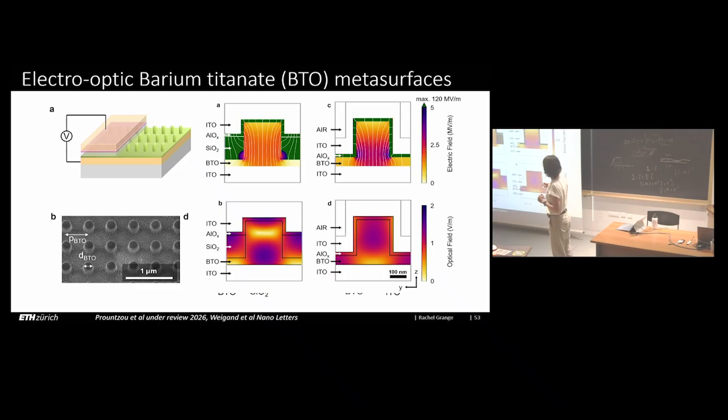Sometimes we have to have isolated layers so that we don't have leakage. The sol gel material has a bit of leakage, so it's not so clear what the permittivity is here. We're still trying to measure it, and it's quite challenging, but it's possible to show some electro-optic modulation here.